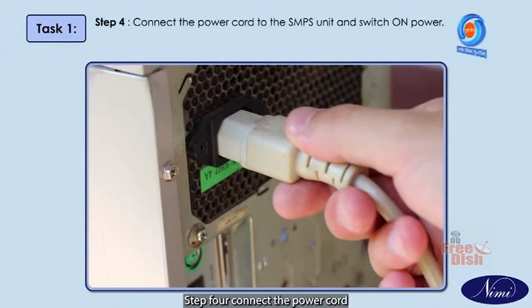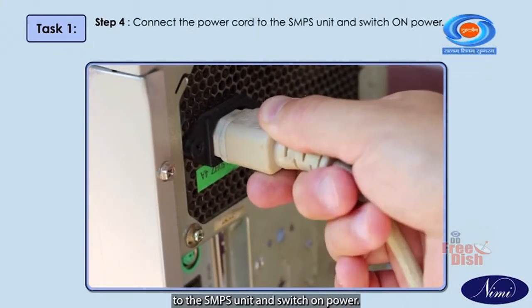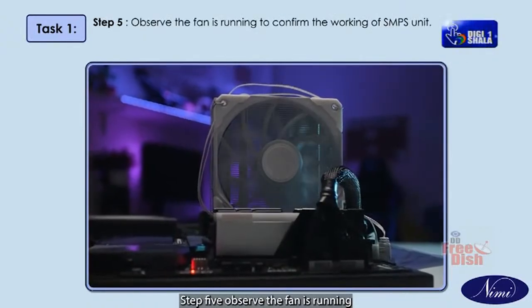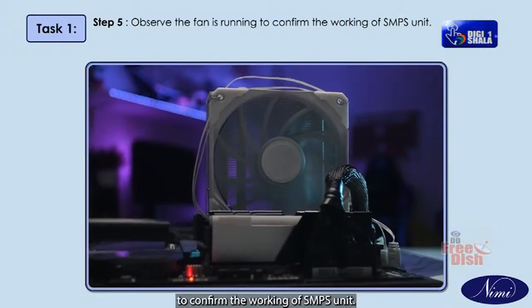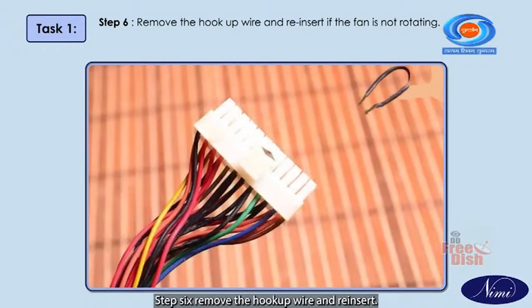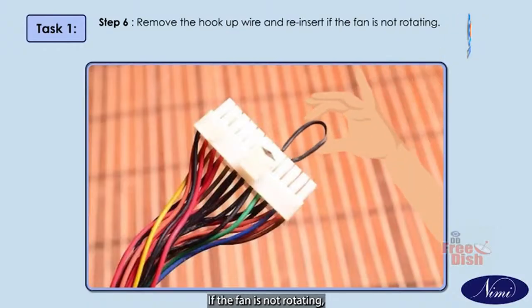Step 4. Connect the power cord to the SMPS unit and switch on power. Step 5. Observe the fan running to confirm the working of the SMPS unit. Step 6. Remove the hookup wire and reinsert it if the fan is not rotating.